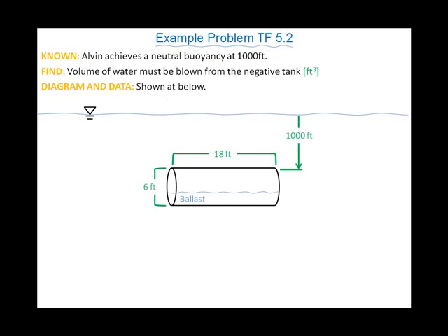Now, inside it's taken on some water in these ballasts, and so we're just going to draw that on there just for a visual. And this overall body, because it's a cylinder, which is a simple body, and we're going to assume it's the same material throughout, has a center of gravity, and that center of gravity happens to correspond with the centroid in this case, because it's a homogeneous simple shape. And it has weight force acting down through the centroid.